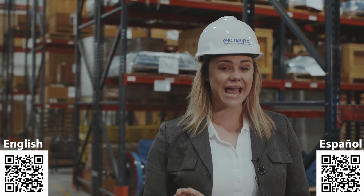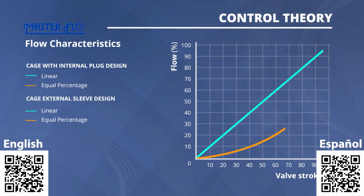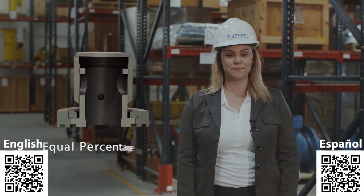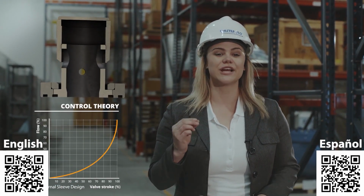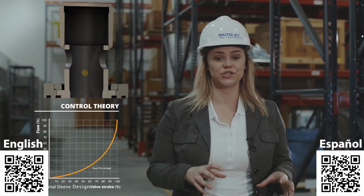In a refinery application, for example, the upstream pressure is typically fixed. The cage with internal plug and external sleeve choke valve designs are both characterized by equal percentage or modified parabolic control. They provide a gradual response in the lower portion of stem travel, delivering a high level of initial control.